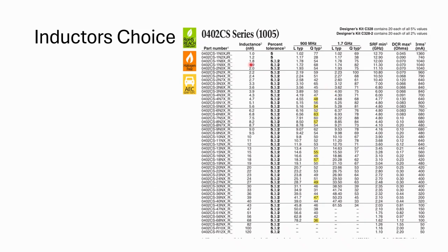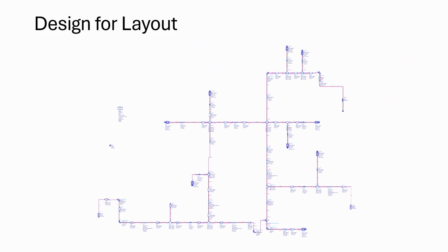As you can see, we added some extra transmission line, and we redrew the circuit so that it will be easier for us to generate the layout. For example, we flipped these like that, and we added some corners. After layout, the result is as follows. S11 is still good, S21 more than 12, stable, and noise figure is less than 0.8.